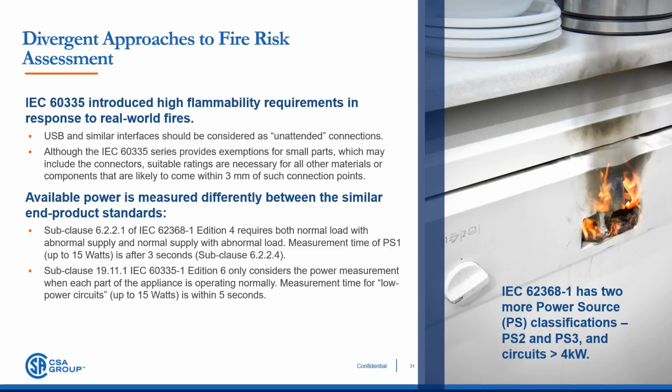Unlike IEC 60335-1, IEC 62368-1 further differentiates power source compliance criteria beyond PS1 to 2 additional categories of PS2 and PS3, where for instance PS2 must not exceed 100 watts in 5 seconds.